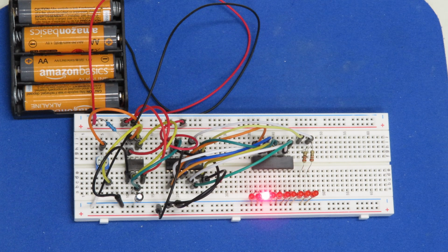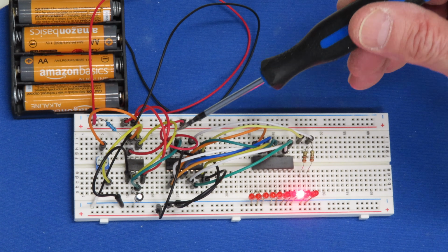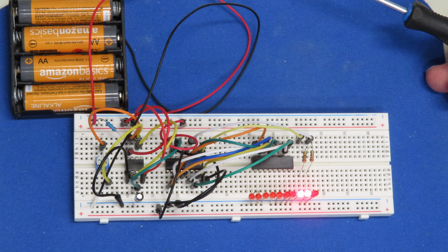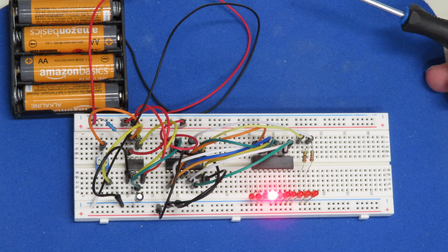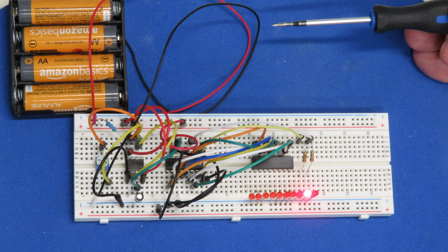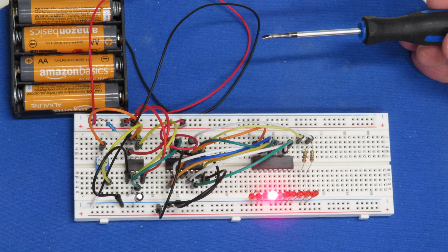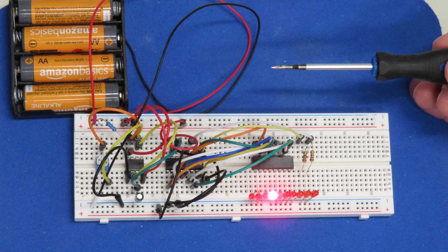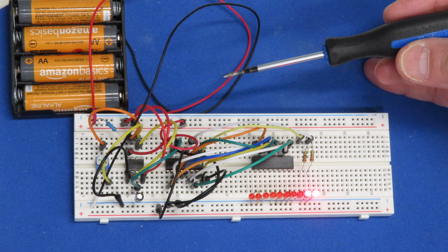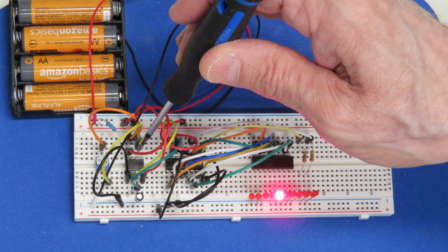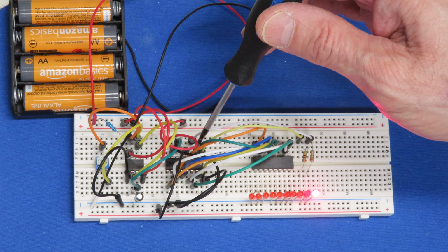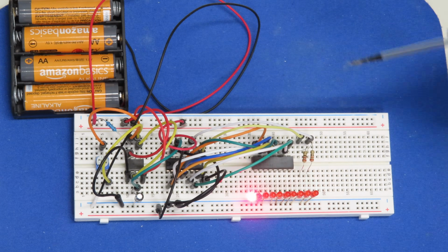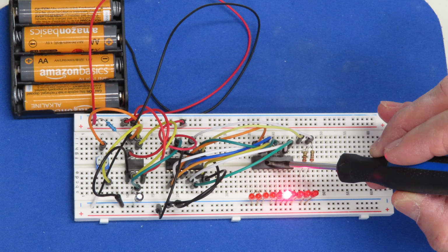So here's our LED chaser wired up onto a solderless breadboard, and I want to point something out on this breadboard that may be a bit confusing, because our design had two integrated circuits in it, the 555 and the 4017 decade counter, and yet it appears that I have three integrated circuits on this board, but that's not actually true. This, of course, is the 555 in the 8-pin package, and over here, buried under this mass of wires, is our 4017 decade counter.